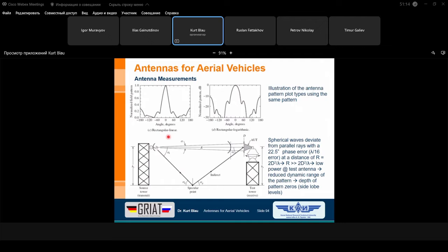But in our case, we can see here plus minus 70 degrees. We have 0, this is 90 degrees. This covers also the 0, meaning in this direction we have no radiation. Radiation is very, very small, lower than 30 dB regarding the main lobe.